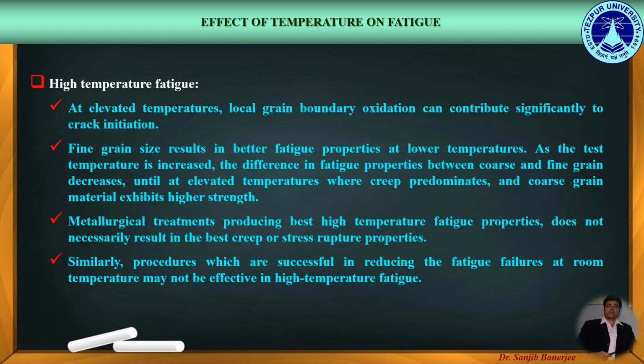Metallurgical treatments producing best high temperature fatigue properties do not necessarily result in the best creep or stress rupture properties. Similarly, we can observe that procedures which are successful in reducing the fatigue failures at room temperature may not be so much effective in high temperature fatigue.